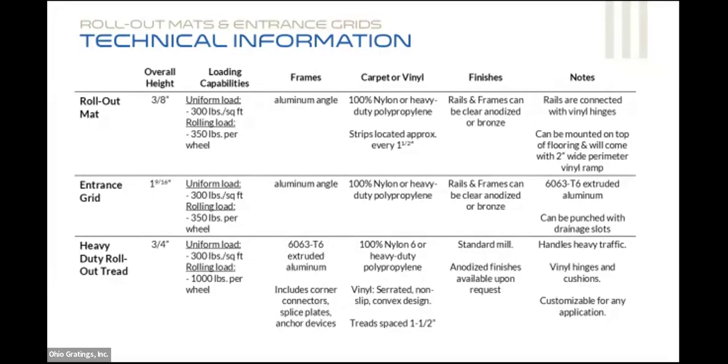You can powder coat these. Just one thing to note when you're doing that is that the anodizing is a surface chemical treatment. It will wear and fade over time. Same thing with the powder coating. There is the potential that it'll fade and wear off there, especially in an entrance mat situation. So just want to make sure that you're aware of that.